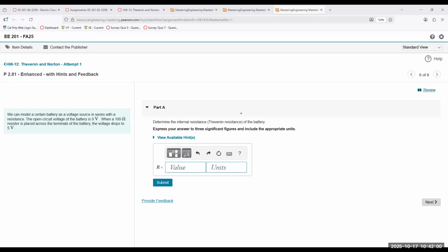In order to find the Thevenin resistance, we find the total Req of the circuit, which is a technique that we've already learned before. Does that make sense to everyone? So RTH is not a new technique. RTH is simply Req as measured between A and B. And that's something that we've already done.